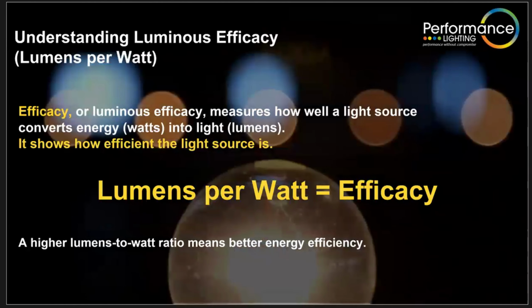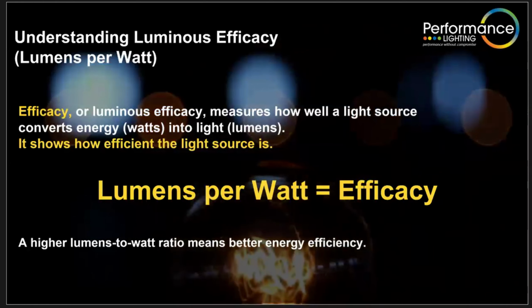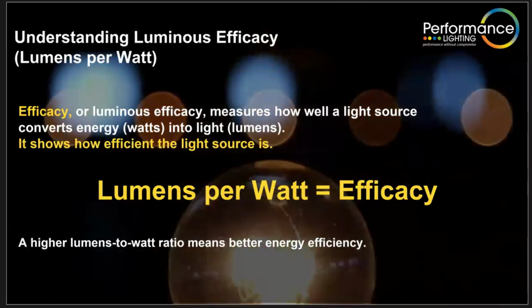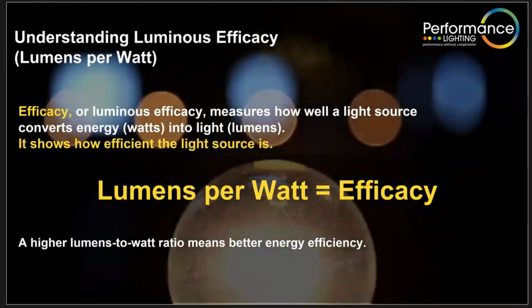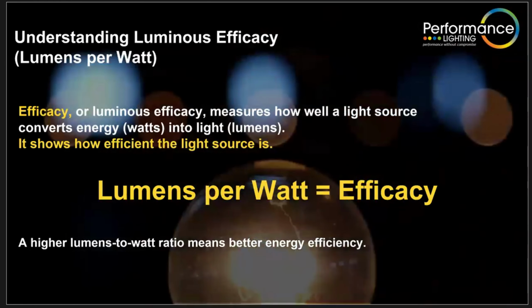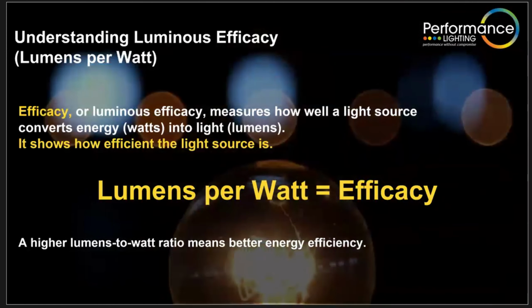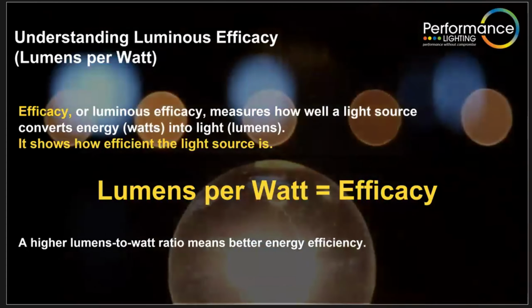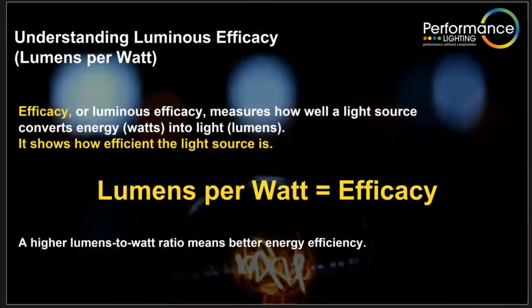Whereas now LED is so much more diverse. A 5-foot LED luminaire can have a lumen output of something around 2,000 to 3,000, up to 15 to 20,000 lumens. Not looking at the wattage right now, but 5 foot in fluorescent was very, very rigid, whereas 5 foot in LED can be so massively varied. That's why it's important to talk about A, the luminaire design, but also B, the lumen output that you're looking for rather than the wattage.